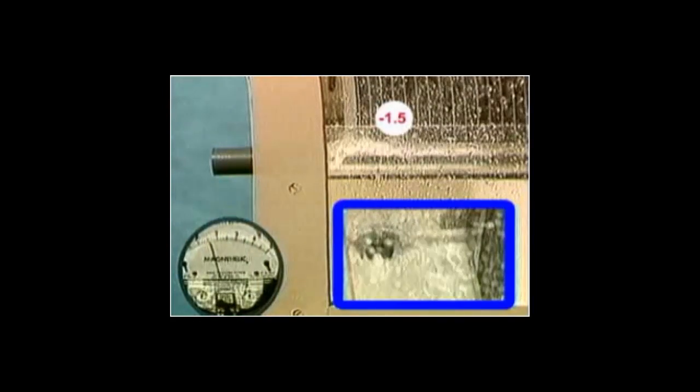Even greater problems arise when systems are operated at a more negative pressure. Here, operation is at a negative 1.5 inches of water. Systems are often operated at this or more negative pressures. As can be seen, condensate blowing becomes intense. Flow cannot occur at this pressure because water will overflow from the drain pan before drainage can begin. Also, as shown by blue paper placed in the blower discharge stream, water particles can be carried into the ductwork and cause damage to insulation and other components.